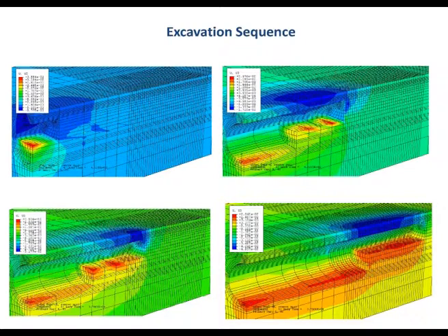The issue is that just because you spray shotcrete on it and there's some steel there, it doesn't mean the thing is fully supported, because it's just cement paste when you first spray onto it. It takes 3, 4 days, maybe 7 days, 8 days to harden to the point where it can actually give you some support. You know what I mean? So in fact, you think about it, if I leave a gap of 1 meter, the effective gap may be 8 meters because you need about 7 to 8 days to harden.